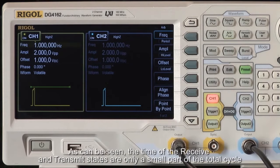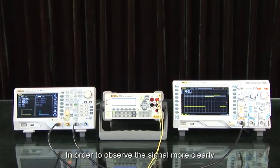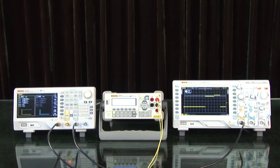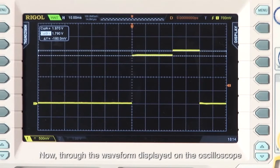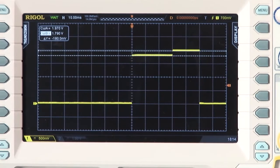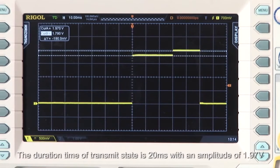As can be seen, the time of the receive and transmit states are only a small part of the total cycle. Next, let's measure the signal in each state. In order to observe the signal more clearly, we connect 2 identical signals to the oscilloscope and multimeter. Now, through the waveform displayed on the oscilloscope, we can see that the duration time of the receive state is 30 milliseconds, with an amplitude of 1.79 volts. The duration time of the transmit state is 20 milliseconds, with an amplitude of 1.97 volts.